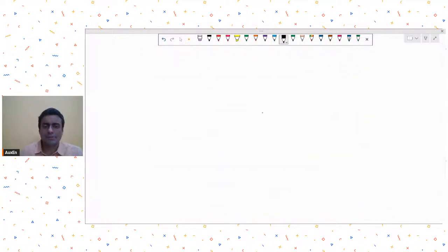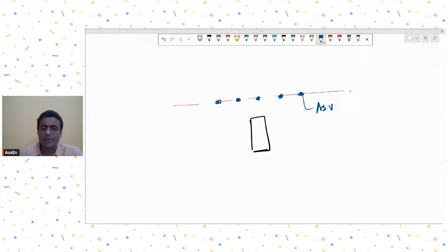So for example, this is my column, and suppose on this edge you wanted to provide one-way shear reinforcement. So these will be your legs, and this becomes your ASV. Understood? Then when you distribute it, suppose this was my local axis 1, this was my local axis 2, SAFE local axis.